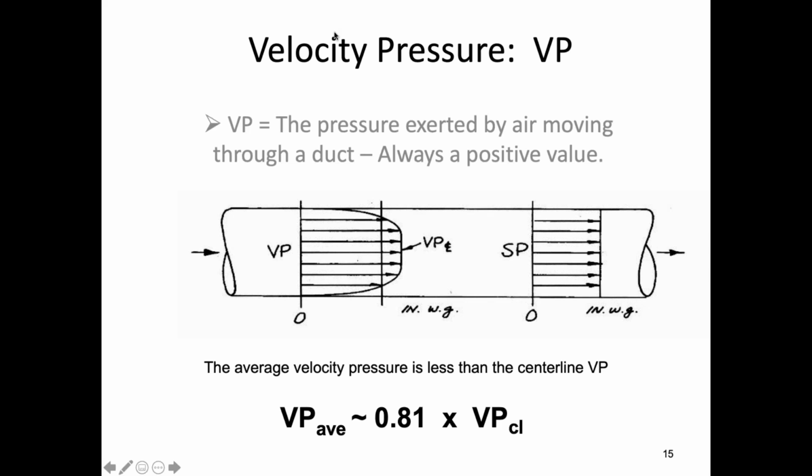Well, the way you adjust for that, there's tiny little holes on the side of this. I'll pass it around, you'll see it. It's actually two tubes, one tube inside of another tube. At the same time that you measure the air flowing into the tip here, total pressure, velocity and static pressure, you have these little holes on the side that, since the air is passing over them, you're only measuring the static pressure. So you can connect this to the other side of the manometer.